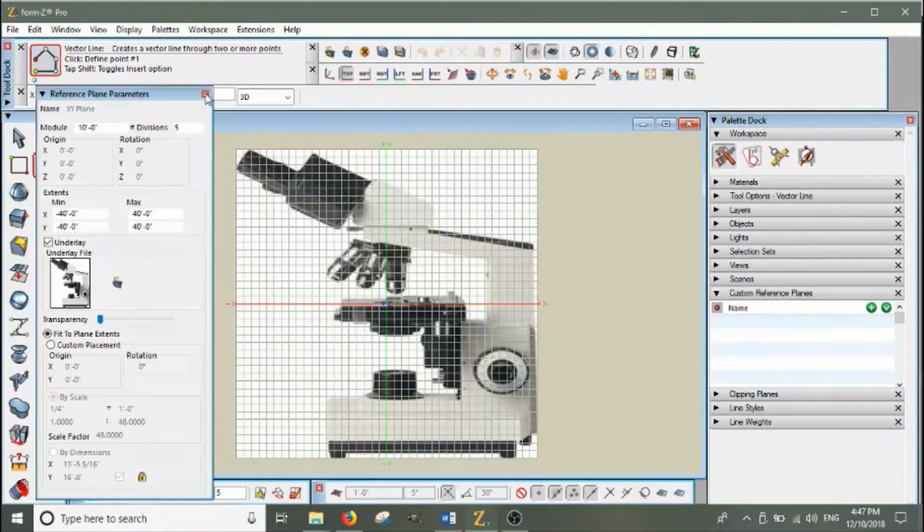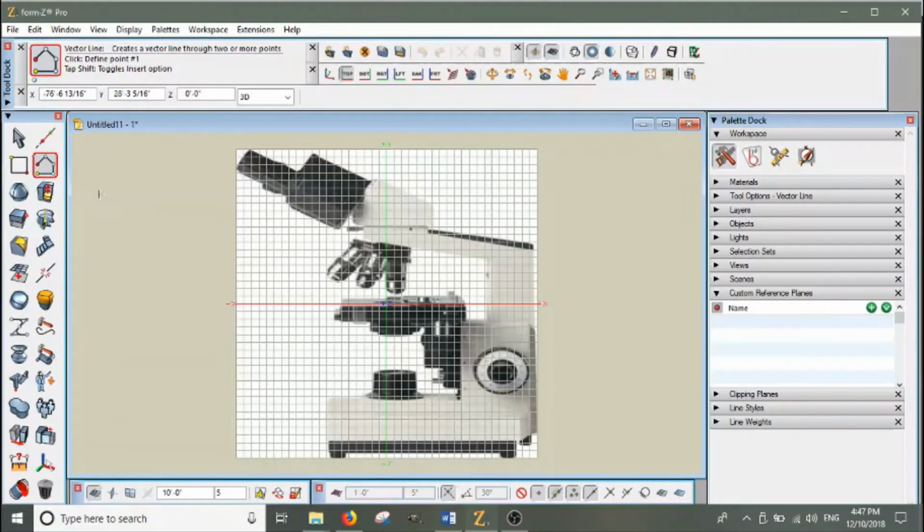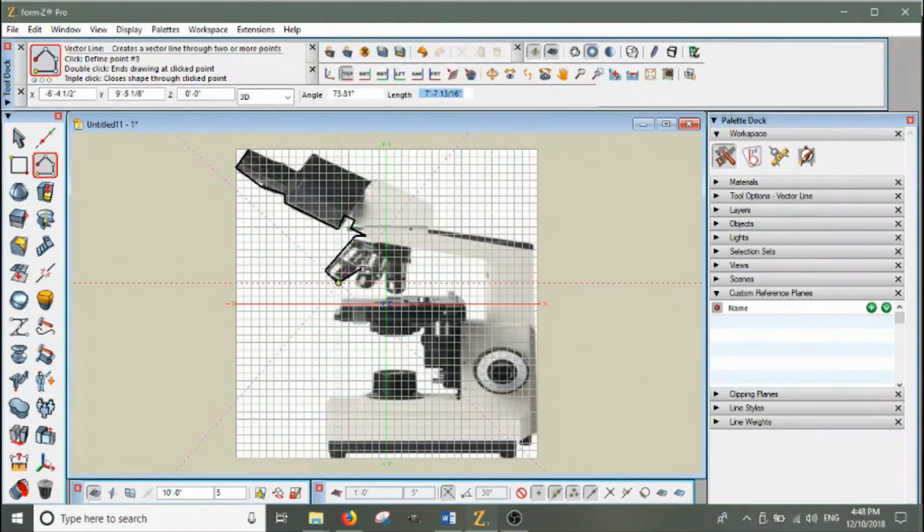So to give an example of how you can do this kind of rapid prototyping, let's use the Polyline tool in order to quickly approximate the shape of this object. Now, as you're doing so, make sure that you know which of your snap features is on, so that way you understand why the lines are or are not going in the direction that you expect them to. So you can see with this tool, we can quickly make the rough shape of this object. I'm going to turn off a couple of the snap features just to make this go a little bit more quickly.